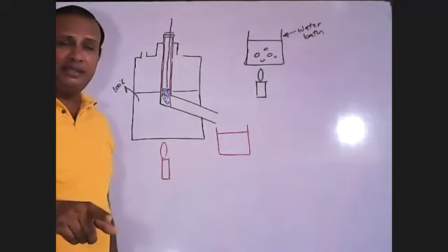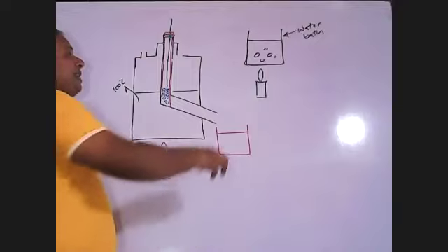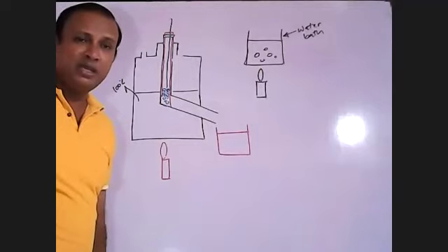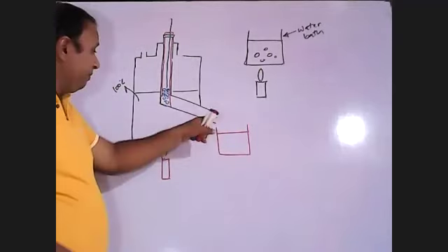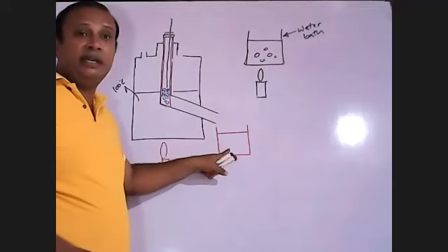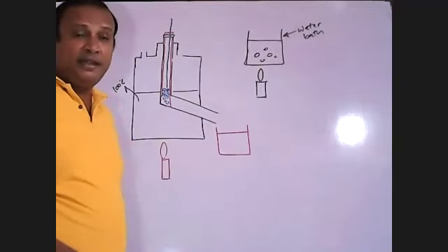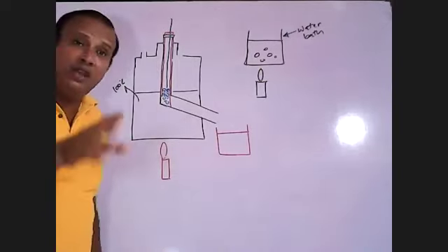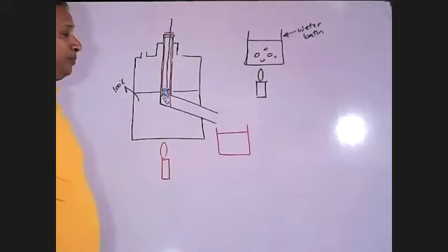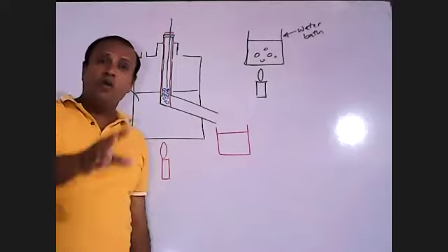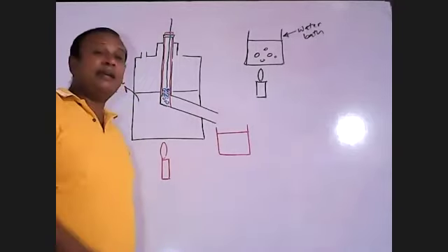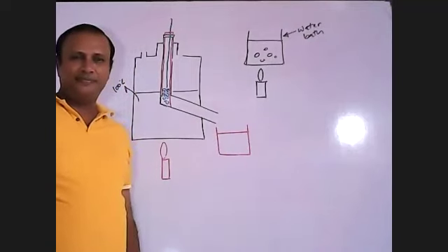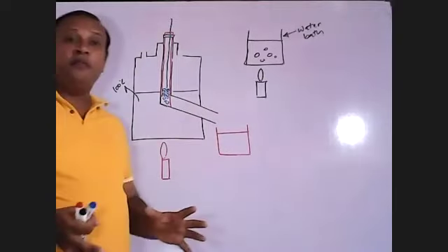The problem is, if you take them out, there will be water outside the metal ball. So if you put them immediately into this calorimeter, the lead shots are not the only ones who give heat to this system, because they come with water.